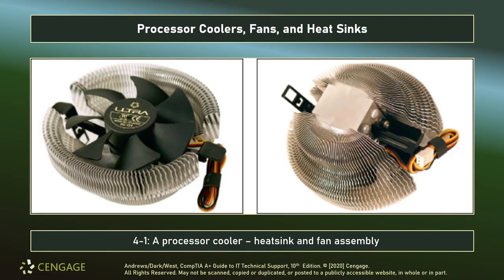The tighter the space between the cowling of the fins and the edges of the blades themselves, the more generation of downforce is able to be provided by the fan, or upforce depending on the direction of flow. So usually designers will leave a minimum of space there just for tolerances and things like that, because these are mass produced, but they'll be pretty tight comparatively. You know, you can get a piece of paper or the end of a pen in there, but you're not going to be able to get a finger in between for the most part, except for, as you can see, the spaces where the clips will move, because usually that requires a little bit more work.